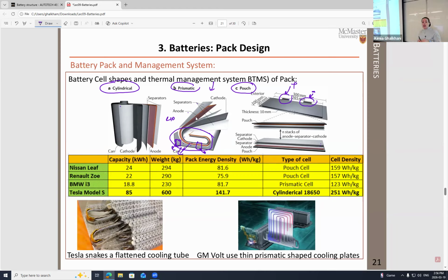Cylindrical is always like folding the same layer. Cylindrical couldn't be an individual layer. So in fact, I would say the structure of cylindrical batteries and prismatic batteries is very similar, because both of them are a very long sheet of cathode or anode or separator, but the method of folding is different. Make sense? What's the difference between their structure?